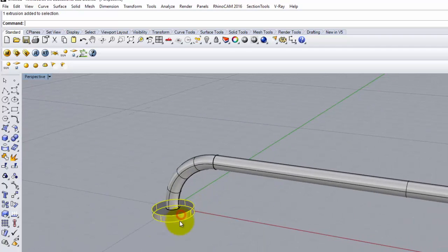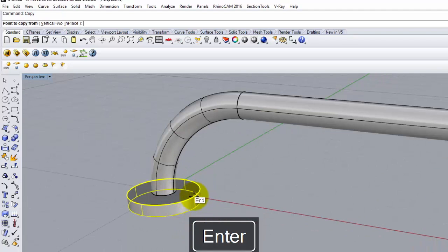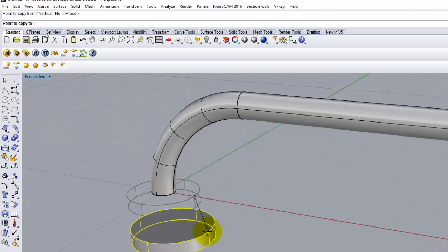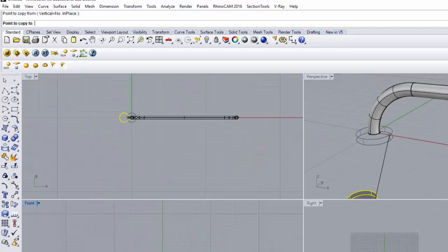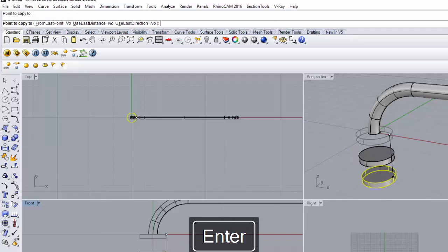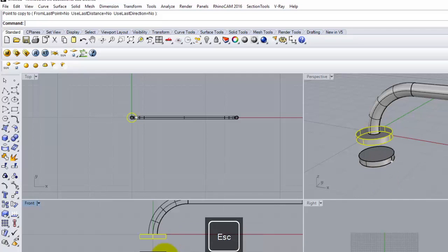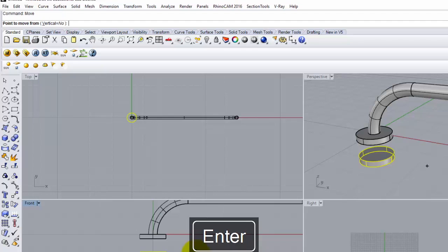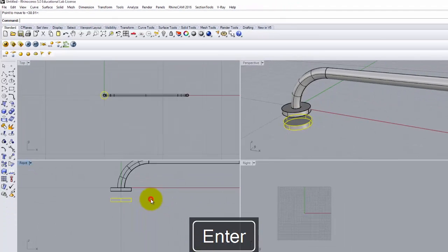Okay, I'm going to take this, and I'm going to copy this down. And so we'll go down maybe 1 inch. I'm going to switch my view, though, into this view. Turn on ortho, and then I'll type in 1 inch so I can see where that goes down. Actually, that should have been 3/4 inch. Let me put it back. 0.25 inches. There you go.